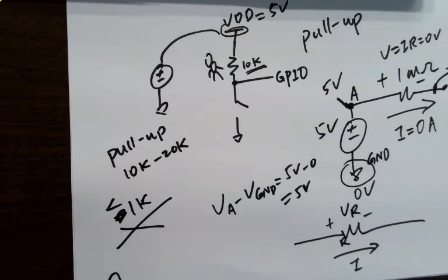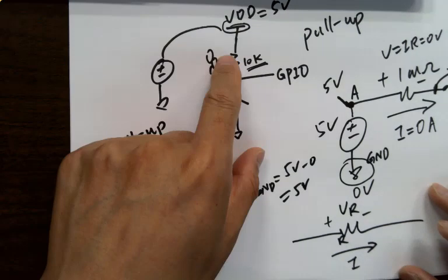Because we want to resist, because the chip needs to hold down that GPIO, and we don't want the chip to take in a bunch of current, so we need it to be weakly pulled up. Yeah, same thing. We don't want a high current running through the circuit. Because low resistance will give you a high current.